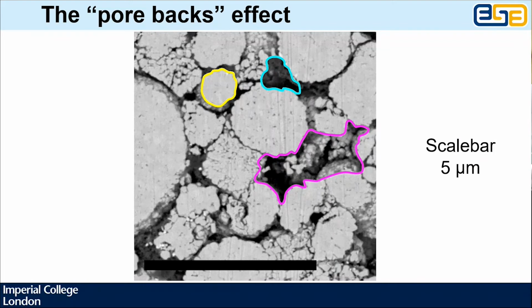One is that the battery electrodes aren't quite as rigid as the sintered ceramic scaffolds of SOFCs, so the epoxy might distort the microstructure. Another problem is that the epoxy might not go into all of these nano pores. It is a viscosity limited process. And the third problem is that even if it does, you then have to try and segment the difference between a carbony polymeric binder and a carbony epoxy resin that basically have a very similar signal under electrons or X-rays.